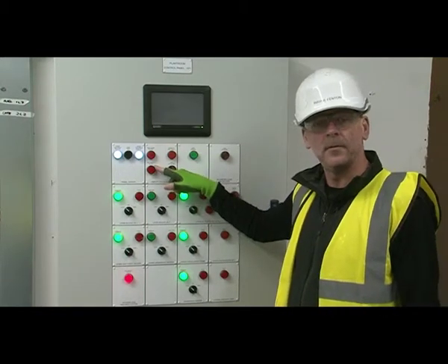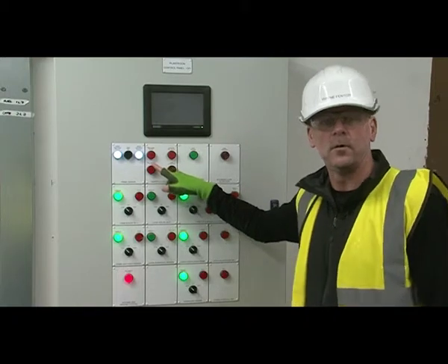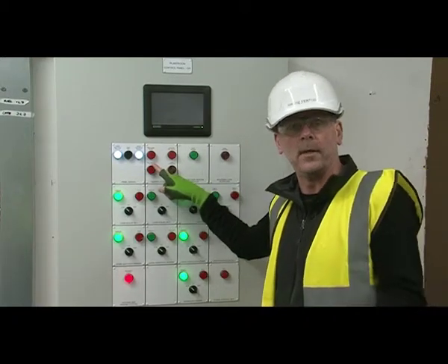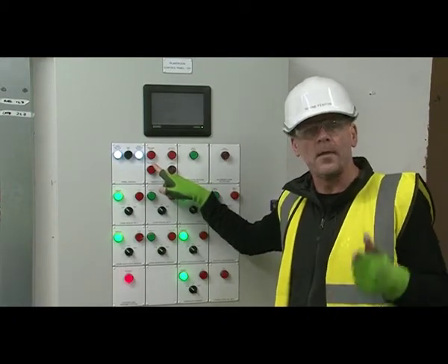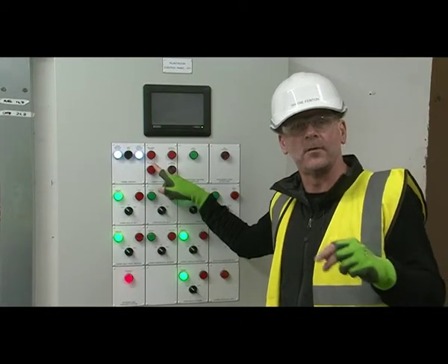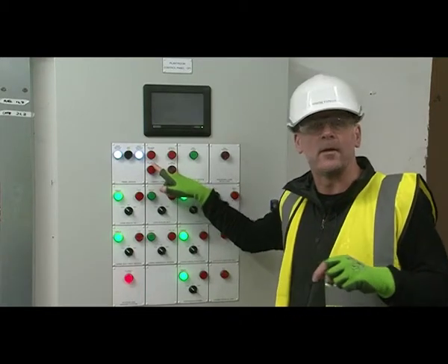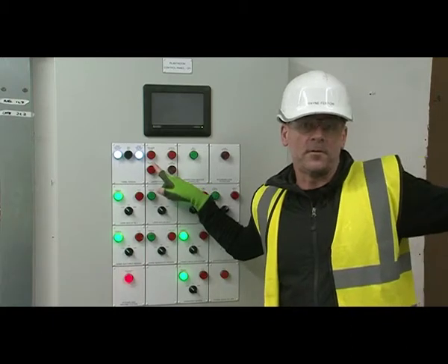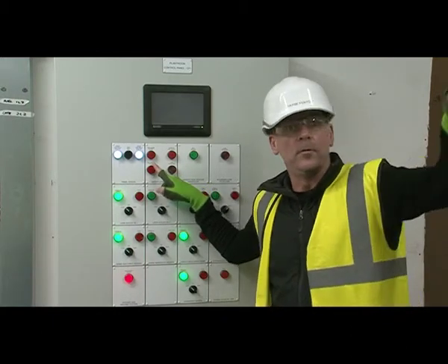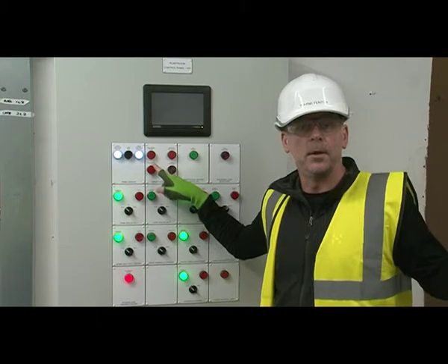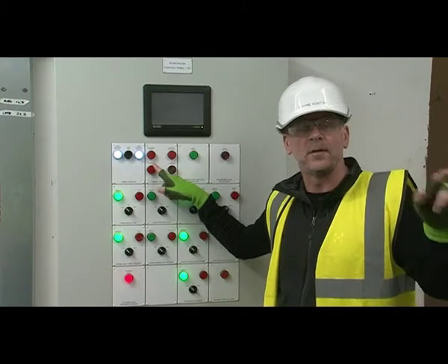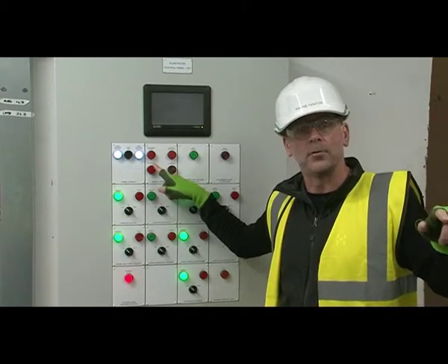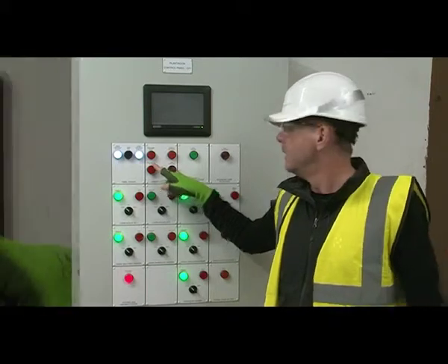Gas safety active, that will shut down the gas to the building, that's the plant room and the kitchen, and that goes off if any of the safety devices that are linked into that circuit are activated. That includes emergency stops at the exit to the plant room, thermal links above each boiler and burner, and also we have 2 gas detectors in this plant room, one for natural gas and one for CO detection.